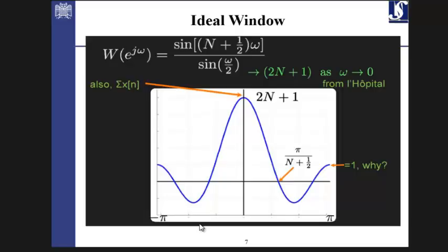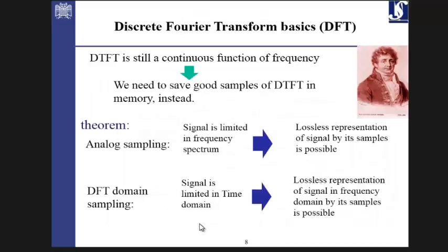You're not starting from zero energy here. So it creates lobes, some side lobes, and you will see in the practical experiments that the rectangular window is not a good window. What we do is normally using other alternatives, like using smoother windows, Hamming window, Kaiser window, or so many different other things.